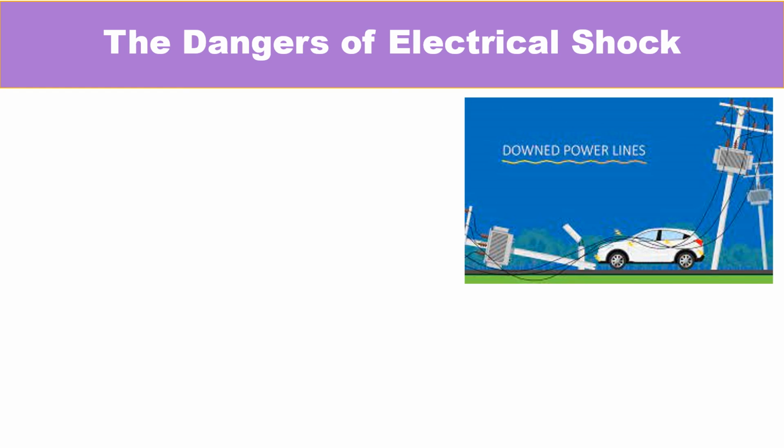And if you're in a vehicle, and some power line goes through, I will tell you right now, stay in the car, because the car is a conductor. If you think about the electron movement, they will pass through the car and then go to the other area. If you open up the door, you are creating another short circuit that can damage you.